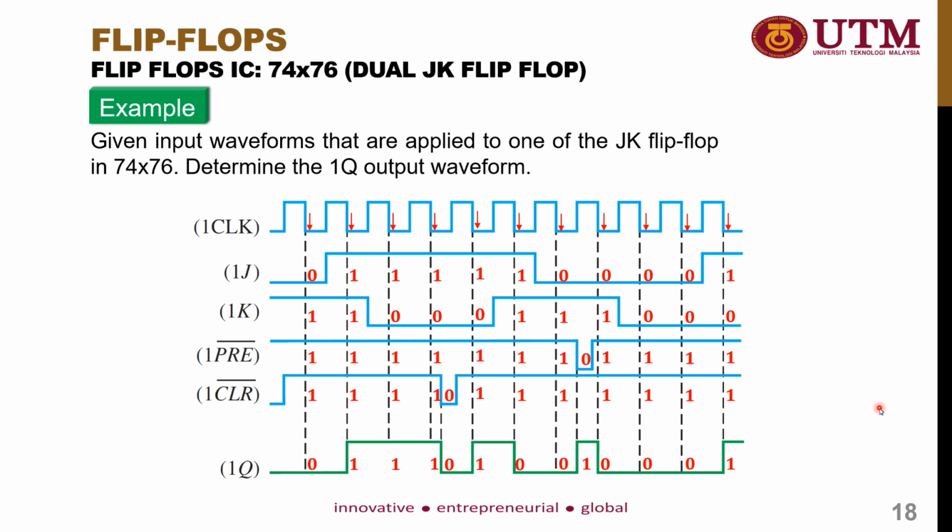So from this waveform, in order for you to answer this question, if the question is about drawing the output waveform for a synchronous flip-flop, what you need to know is that first you need to observe the initial condition. And then you need to define the type of flip-flop, whether it is positive edge triggered or negative edge triggered. So for this example, it is negative edge triggered. So next we must observe what the input is at the negative edge trigger, at the first negative edge trigger.